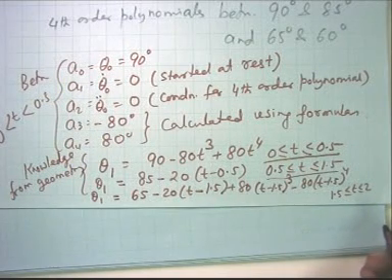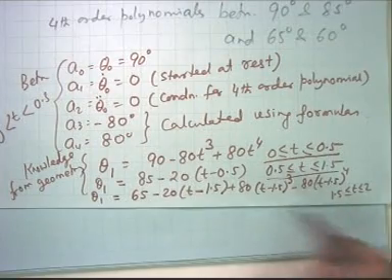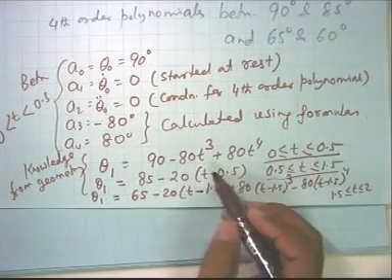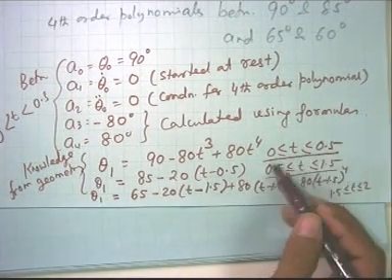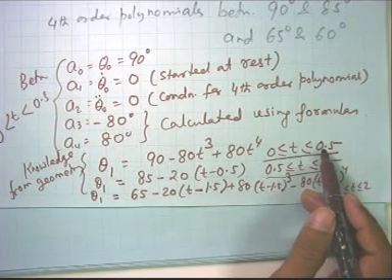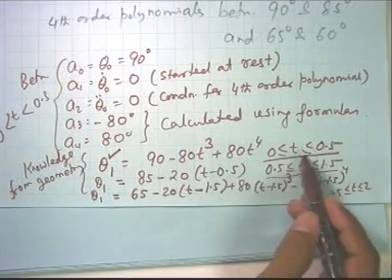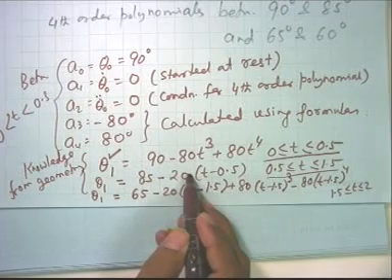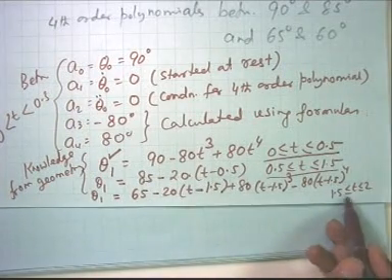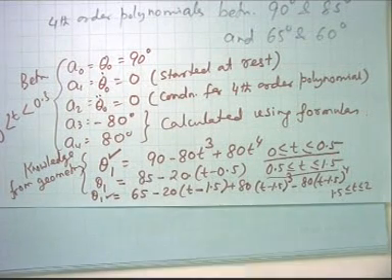When a control signal has to go to the computer, depending on the value of t, it will first check at what period I want to calculate. If it is in this zone it will use the second function, if it is in this zone it will use the third function, and that is the way it will calculate the joint trajectory for the first one.